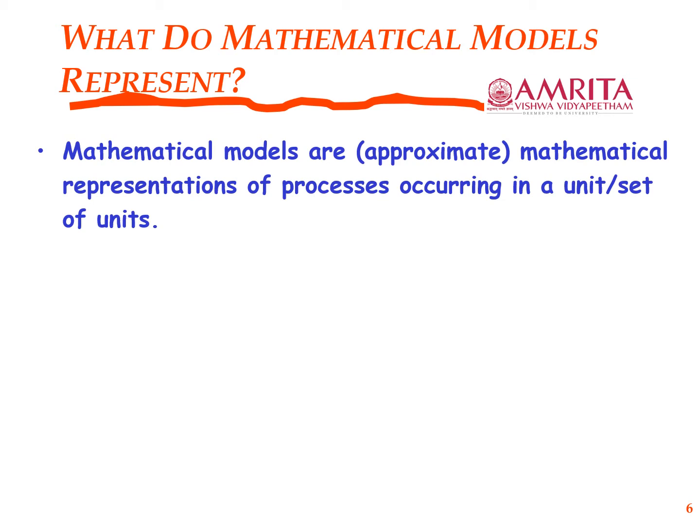So there are multiple side strippers, and there are what are called pump arounds, where some liquid is taken from a lower stage and then pumped back up to a higher stage, which even though it overrides any separation that has been achieved by the liquid coming down, it is now being put back up, right? And that separation is lost.